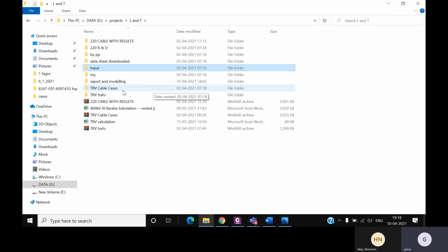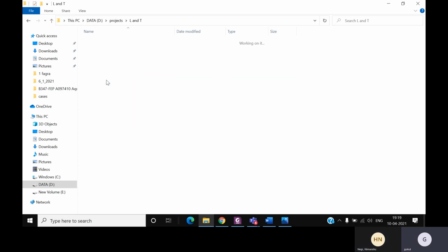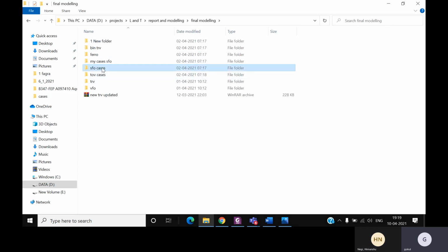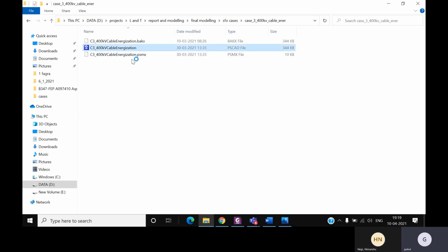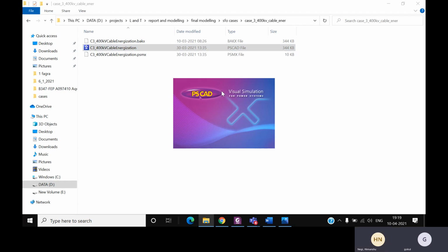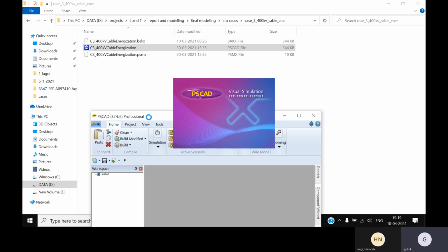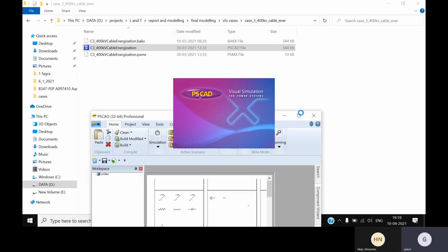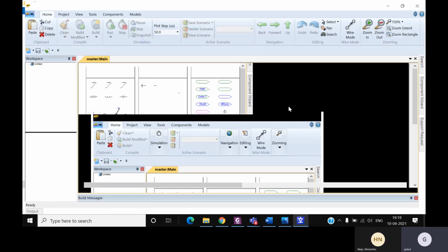No, we have to model the breaker, but the whole one and a half scheme I'm trying to avoid, including the isolators and everything. I don't need any isolator, any bus, any disconnector and everything. I just need the breaker, and that's more than enough. I need a source and the case, whether that's an OHL or cable or whatever it may be, and the corresponding equipment I need. I'll just show you.